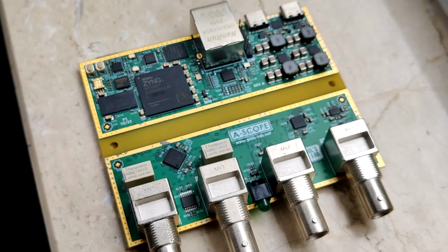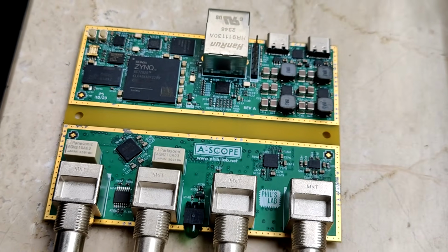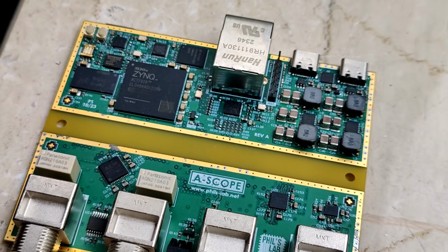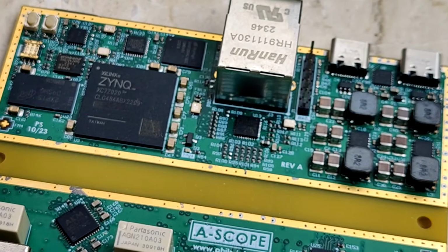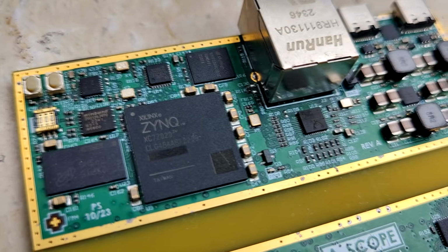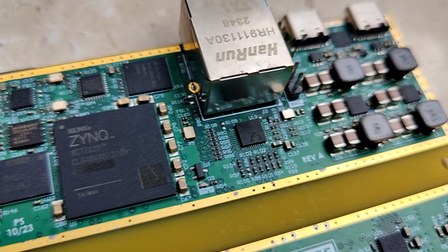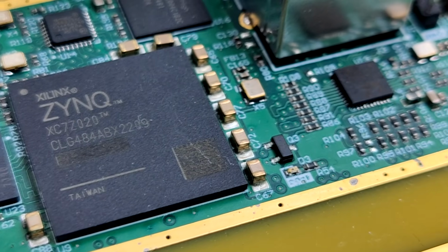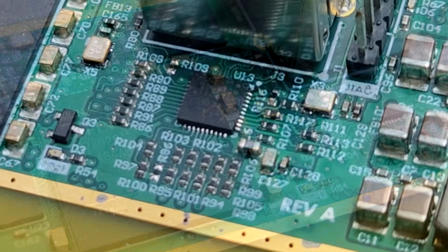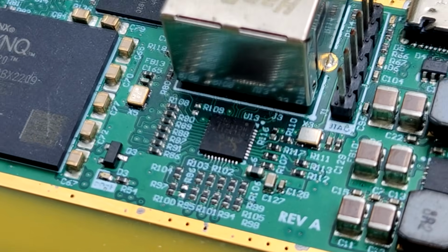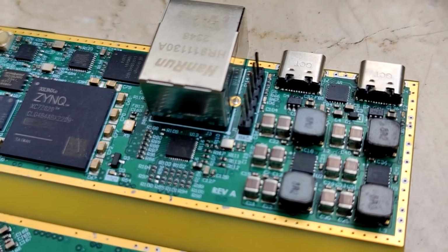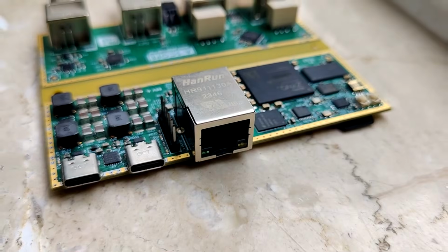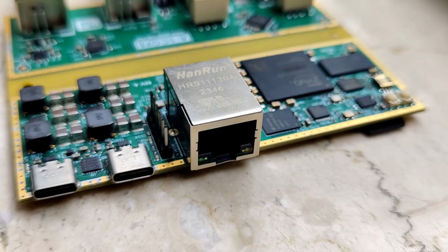In particular, the physical layer, what signals need to go to and from this device, how this is configured, what power supplies it needs, clocking, and so on. We'll also be looking at a real-world board, the board you are seeing here, which incorporates an AMD Xilinx Zynq system on chip, which integrates a Gigabit Ethernet MAC, which on this board interfaces with the Realtek Gigabit Ethernet PHY or physical layer connected via RGMII. Then the PHY connects to a MagJack Ethernet connector.